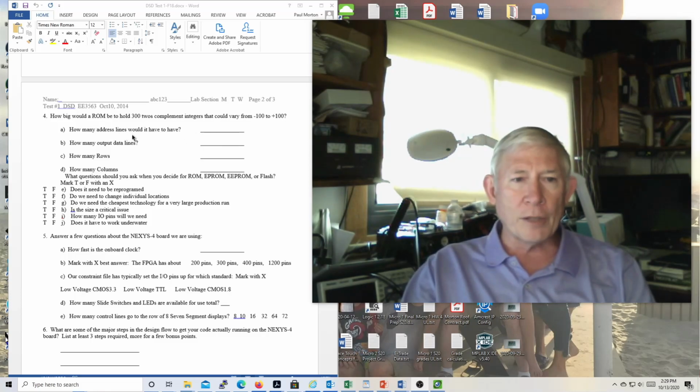and we need 512. So how many address lines? 9. How many output data lines? 8. How many rows? 512. How many columns? 8. Same as the output data lines.